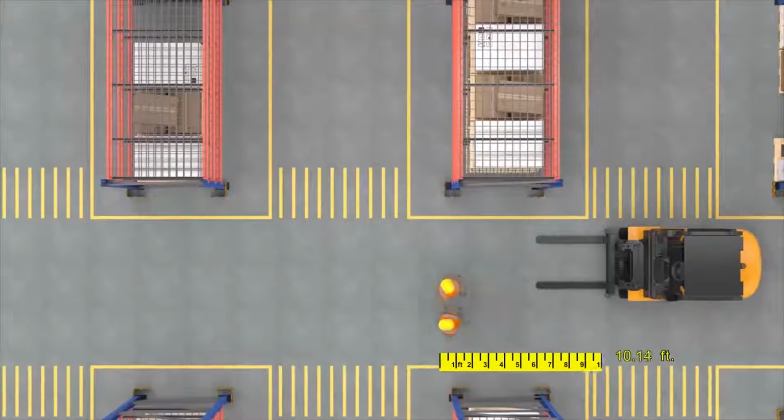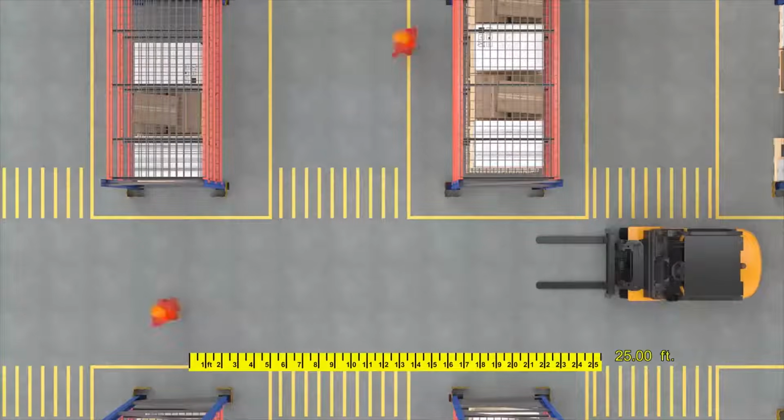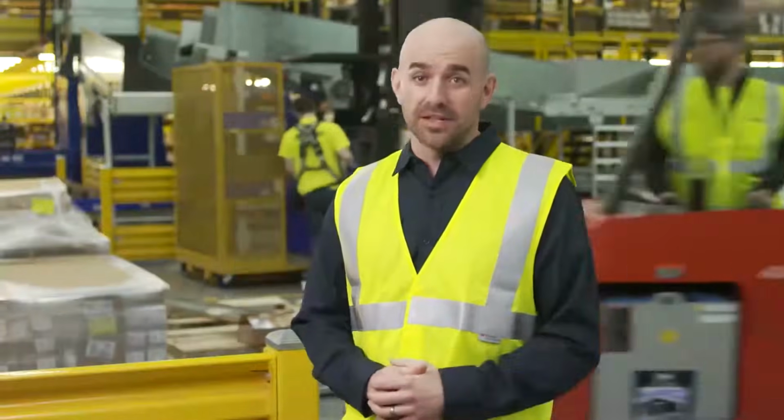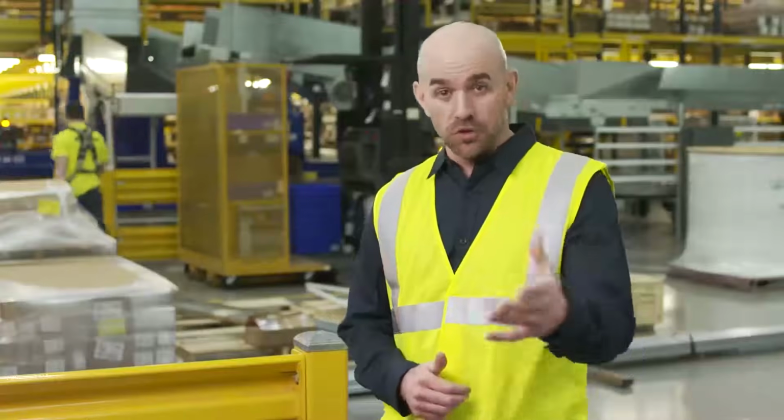Anytime you go beyond 25 feet from the forklift, or if the forklift is ever out of your sight, you've got one more thing to do. Turn off the unit right away or head back and do it. Even if you stay within 25 feet, to be extra safe, it's a good idea to shut the unit off when you can. Follow your company's policy for managing the keys.